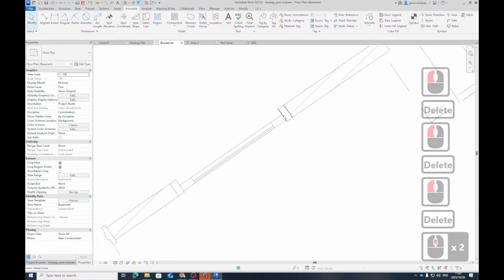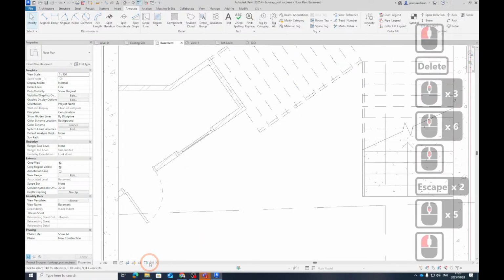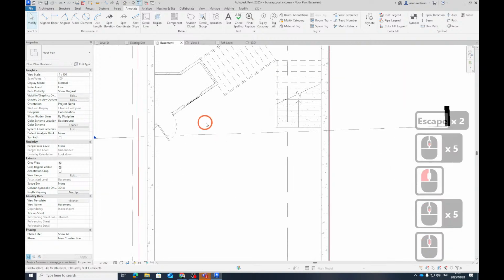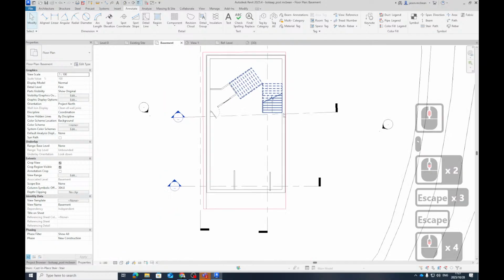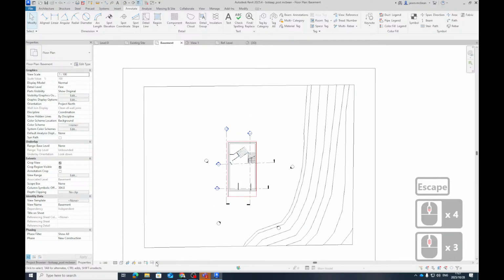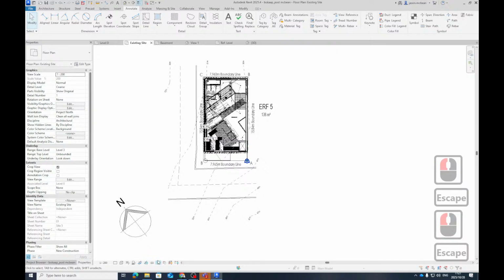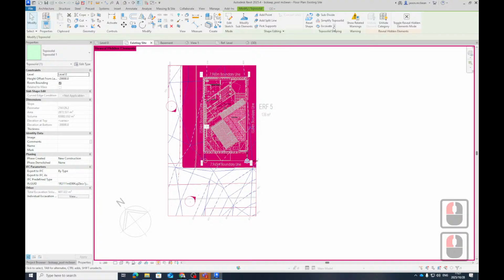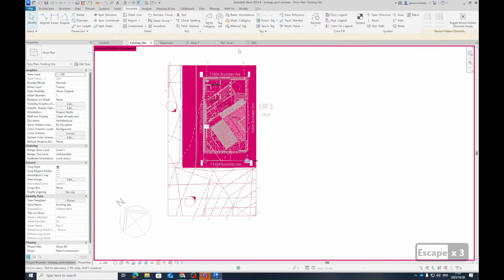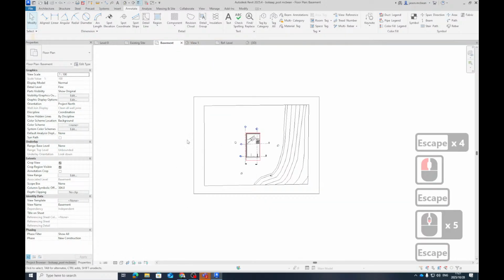And if I've accidentally hidden something in my view, how do I undo? Okay, so if you've accidentally hidden something, hidden as in left click, hide. Yeah, and I'll explain. So now you've got another command. Why am I not seeing it here? It's supposed to be here. That's very strange. There it is. You see this icon. Anything that's hidden, you can now go and select, and so it's either hidden by category or element. So here in that view, I think in basement it should be active. Why am I not seeing that command here? It should be here. That's very strange.